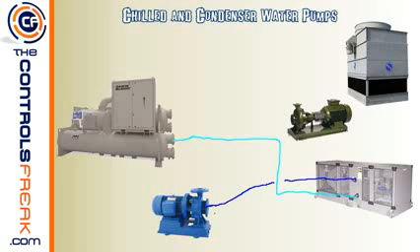And in case you're not familiar with pumps, if you look at this type of pump here, the inlet is going to be this horizontal part here. And there's an impeller in here, so you can imagine it like a boat propeller, but this is an impeller, that will draw the water into the center portion of it and then spin it around and shoot it out the top here. And this is going to go right back inside to the chiller. So now we've pretty much completed the chill water piping.